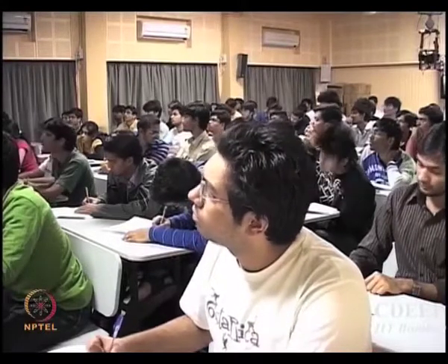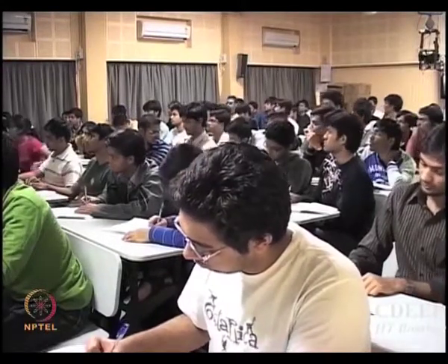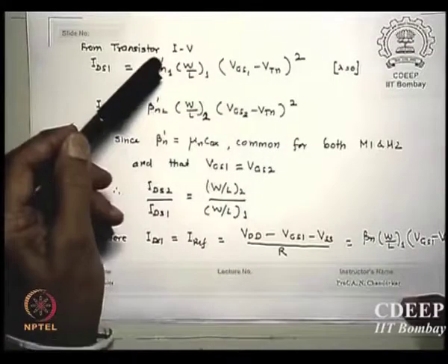Transistors in a technology will have the same thresholds. Is that clear? Unless substrate bias is provided for a specific transistor, its VT cannot be modified. All n-channel transistors, unless stated otherwise, will have the same VTs, or at least VT0 will be the same. All p-channels may have a different VT, but will also have the same VTs. There are new circuits in digital where we are using multiple VTs, but in analog no one has done so so far. So this is common, these are equal.